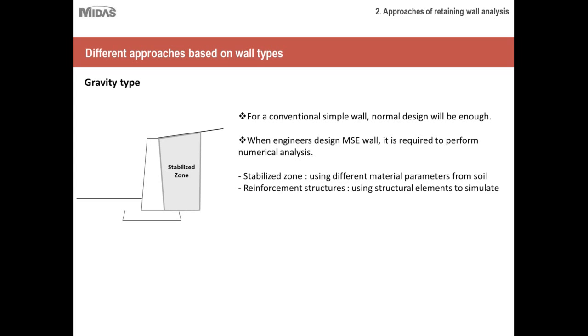But when engineers are dealing with the MSE wall, it is required to perform numerical analysis. And the important thing that you should consider in that is that the stabilized zone that I just talked about uses a different material property or parameter from the remaining soil, and sometimes they are reinforced structures, so you should model them and consider them using structural elements.